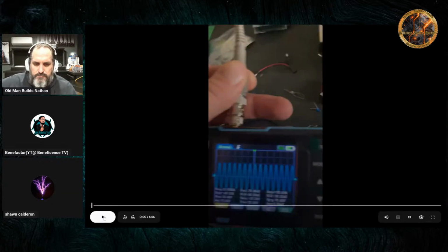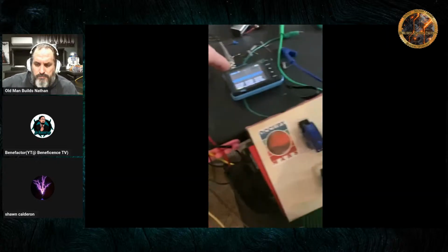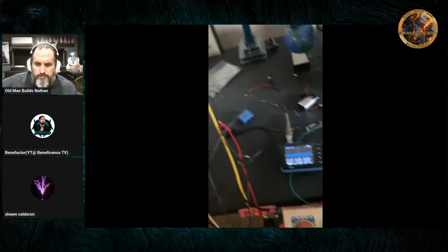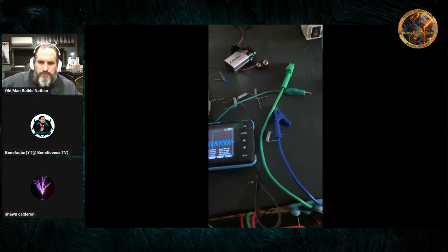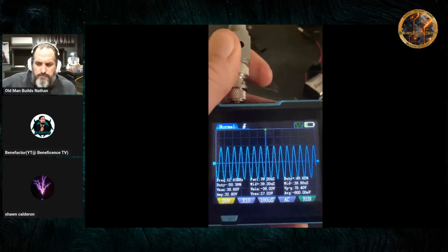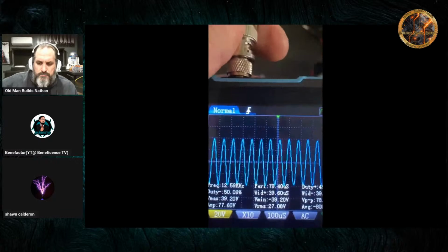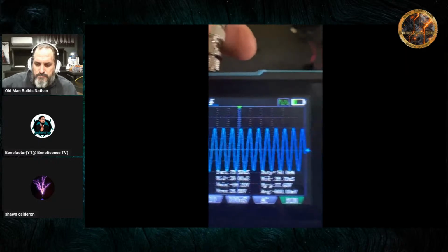Awesome. All right. Can you guys see this? Mm-hmm. Okay, this is the second part. Sorry about that. I had to unplug the load because obviously the load's taking some voltage and it's dividing it, so it's not going to give us an accurate reading of exactly how much is coming out of this capacitor. I think that's why the wave was running low. So I disconnected the load, and now, as you can see, it's got its full potential. It's right up against the middle line, which is the 10-volt line. And we'll change this.